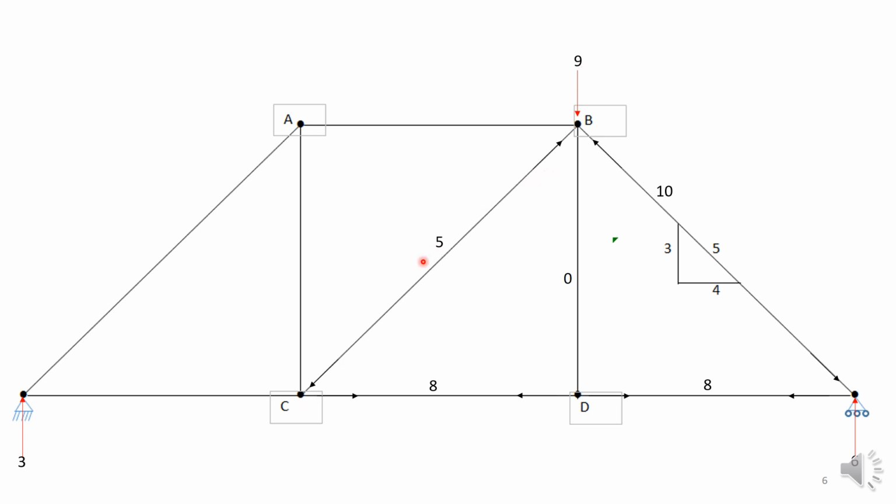And we can look at the horizontal component at B now. Well, the vertical will contribute 0 horizontal component, so you have a 10 here and a 5 on the other side at the same angles. To balance those, you can work out the details. You need a compressive force of 4 units in the top member AB. And let's go to another joint.